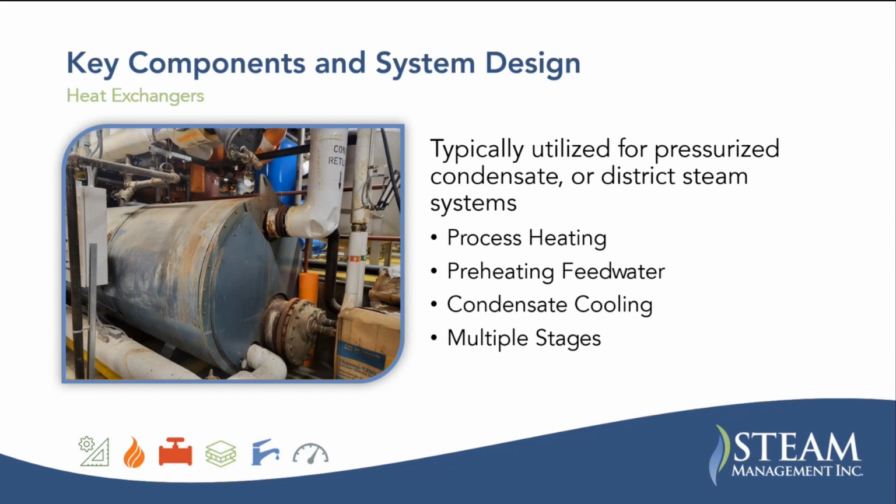Generally, for a lot of systems, I should say, the main goal is going to be just collecting the condensate and getting it back to the deaerator and conserving that heat. So sometimes it does make sense to use a heat exchanger and use the heat for something else, but often you just want to conserve the condensate and all that heat is utilized in the deaerator.